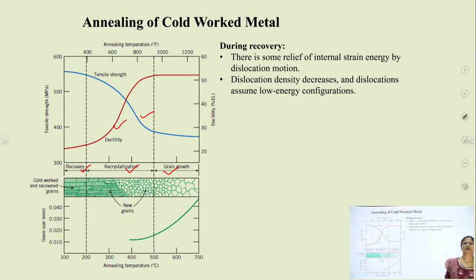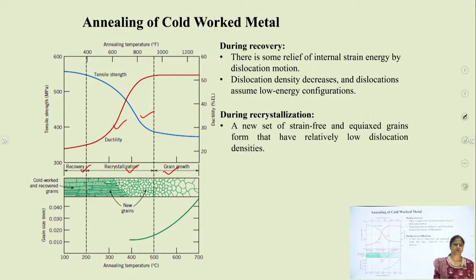So, during recovery, dislocation density decreases due to annihilation of dislocations, and dislocations assume a low energy configuration. During recrystallization, tensile strength rapidly decreases, and a new set of strain free and equiaxed grains form that have relatively low dislocation density.